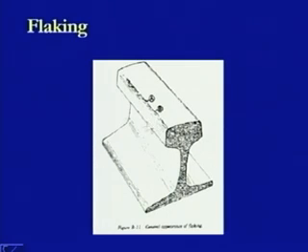So, a chipping sort of condition will be happening at this location because of the striking of the wheel flanges on this side, because the wheel flange is not going up to the full depth of this rail section head, and that is having some depth up to this much level, and this is the area in which that striking will be taking place.